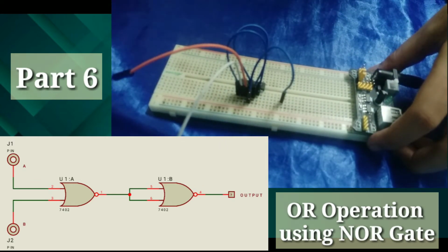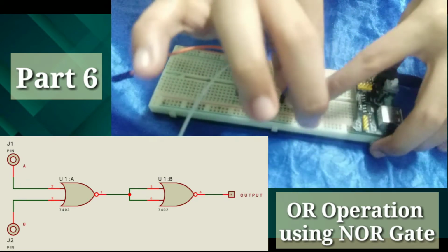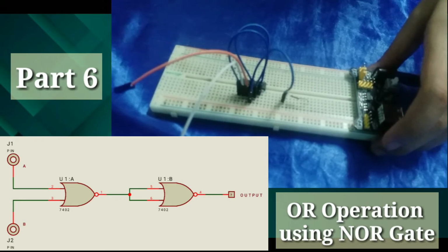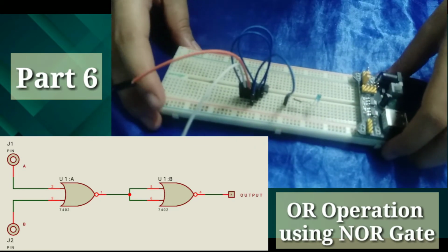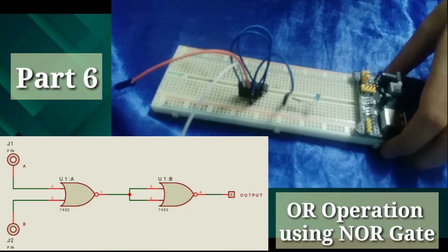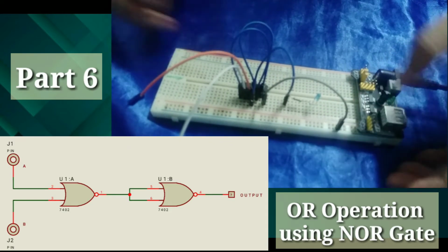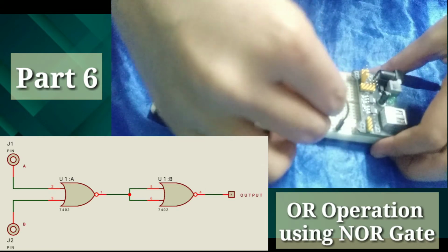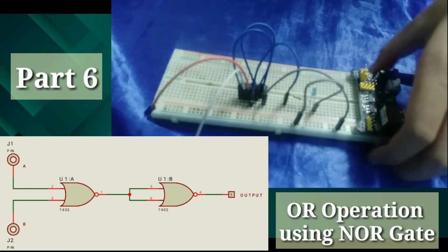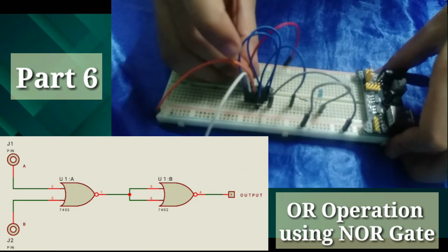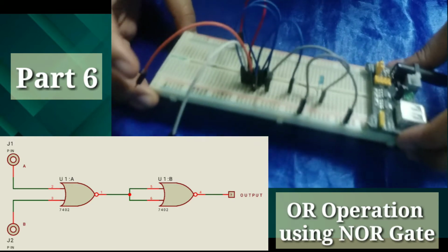Okay. Then, don't forget our 360 ohm resistor for our output. So, here it is. Here we will put it. And then, don't forget our LED, which will be our indicator. Okay? So, don't forget our groundings. Don't forget to ground the 7th pin of our integrated circuit, and the grounding for our resistor so that the LED will light up. That's really needed. Okay? And also, don't forget our VCC connection to the voltage supply. So, this is how our circuit will look for part 6.